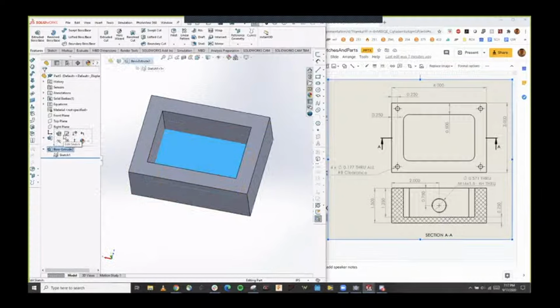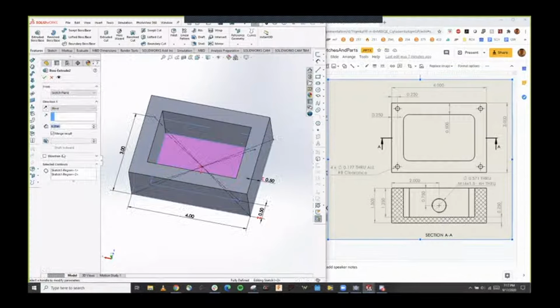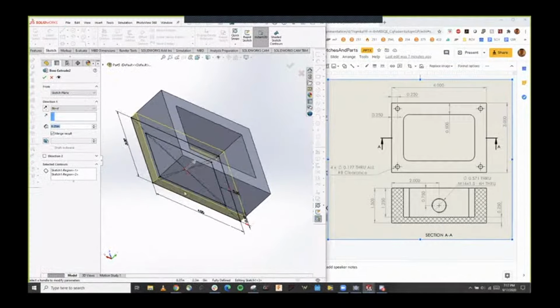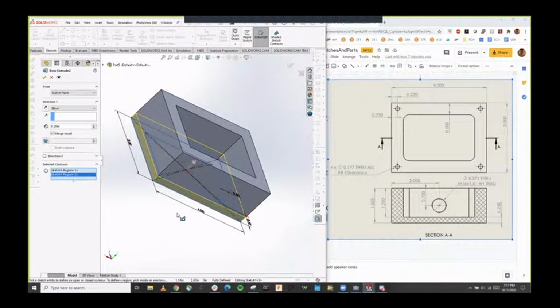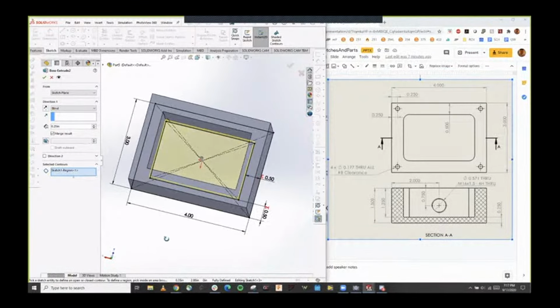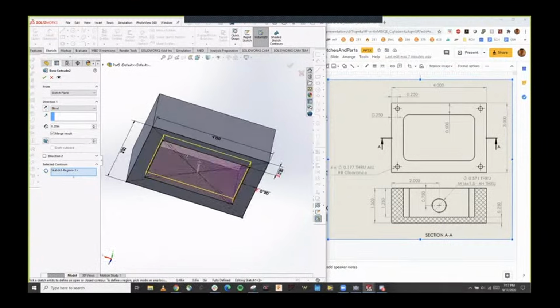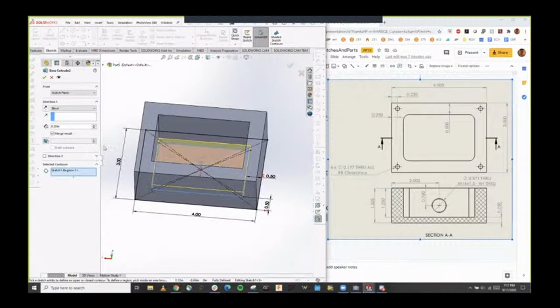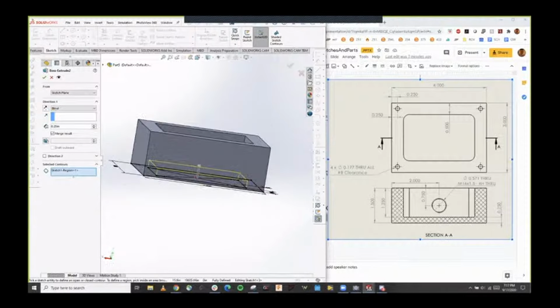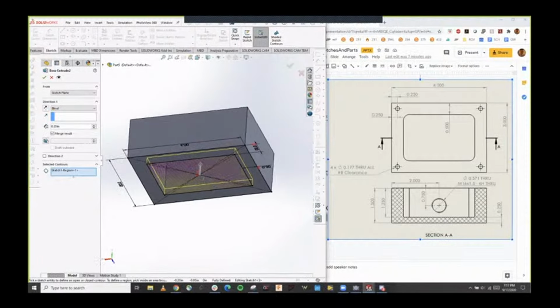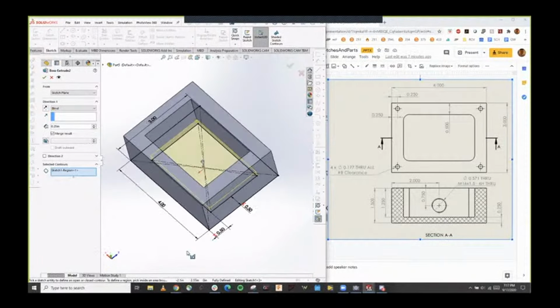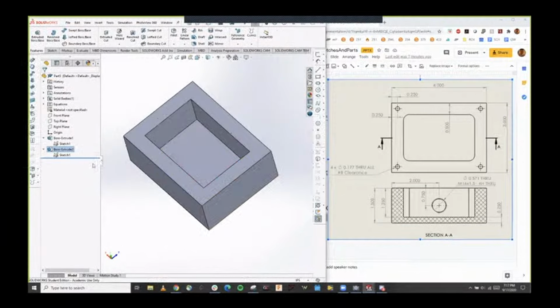Actually, I guess I made a mistake when I was doing this. You don't actually need to extrude this second region, since we already have the middle region defined. But it doesn't matter which one you do, because as long as you have this box checked that says merge result, it will combine them to become one complete body with no gaps or other changes. Merging result also automatically accounts for any overlap you might have, which is pretty nice.